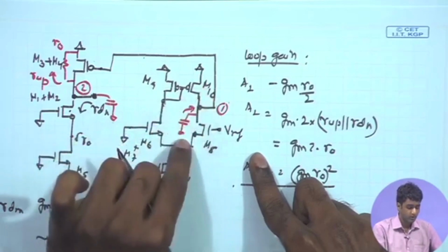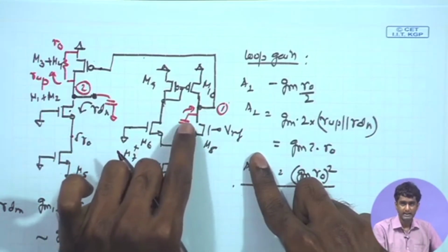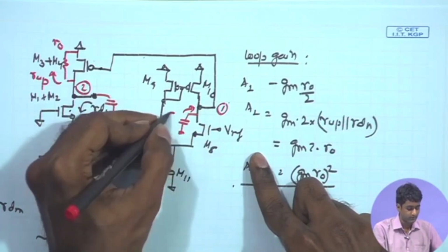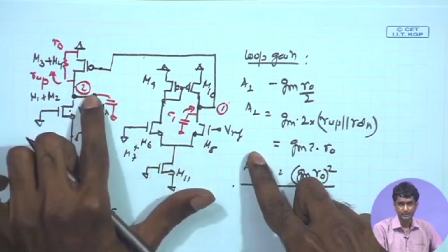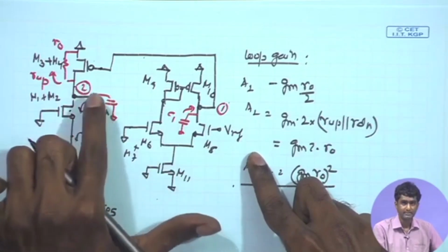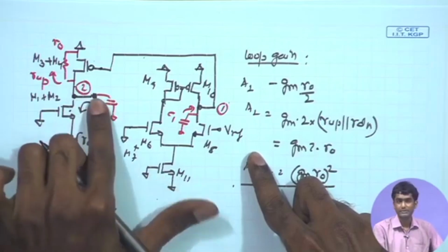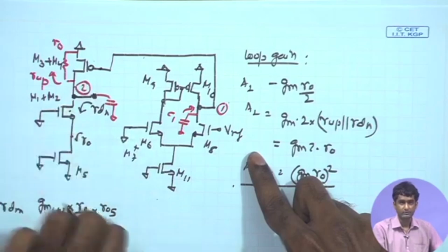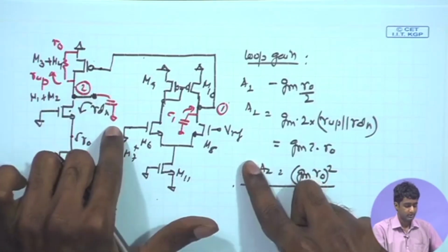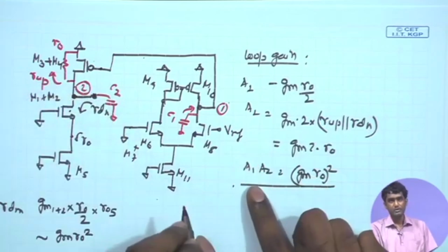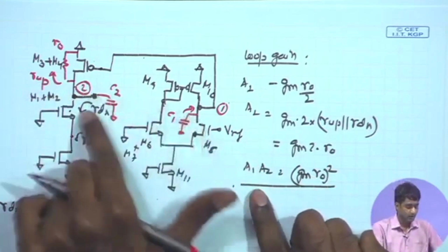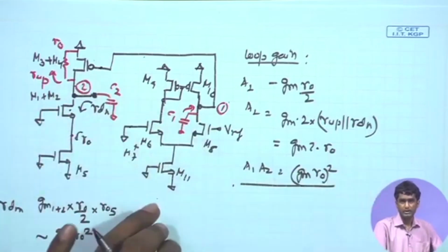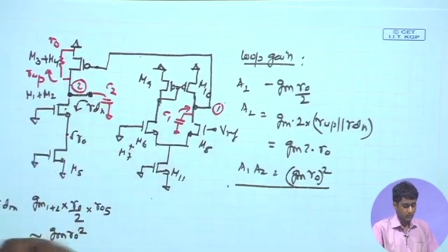So, accounting for all those, we can figure out the overall parasitic capacitance between this particular node 1 and AC ground, and that will give me total C1. Likewise, at the output node, we can find out the total effective parasitic capacitance between the output node and AC ground by counting the contribution of parasitic capacitances for all the transistors, and that is going to count as C2. And we also have the R equivalent at these 2 points. I will call these R1 and R2, and that is how we are going to get the two poles P1 and P2 at these 2 points.